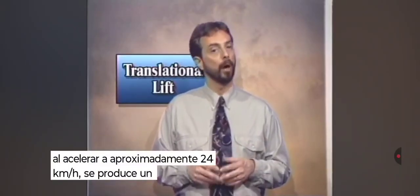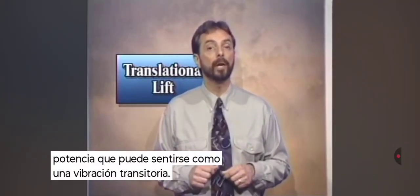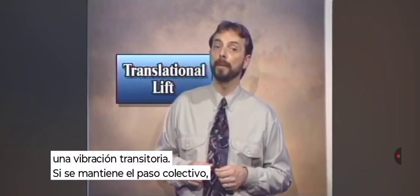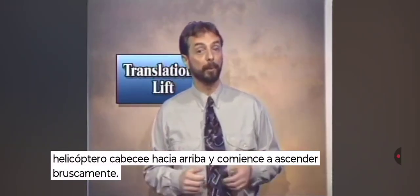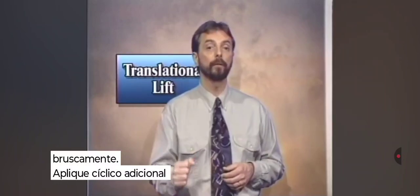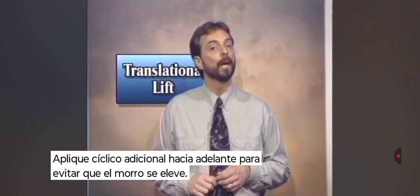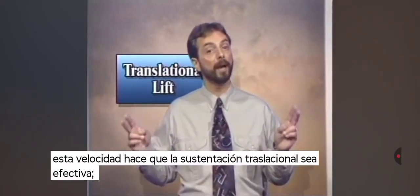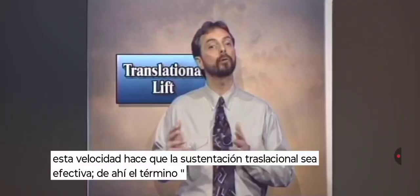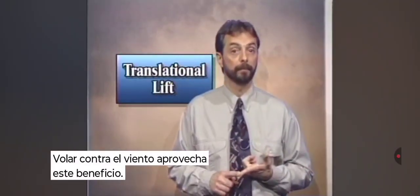When accelerating to approximately 15 miles per hour, a rapid increase in excess power develops and can be felt as a transient vibration. If the collective pitch is maintained, this excess power will make the helicopter pitch up and begin to climb abruptly. Apply additional forward cyclic to prevent the nose from rising. The additional performance available at this speed makes the translational lift effective, hence the term effective translational lift. Heading into the wind takes advantage of this benefit.